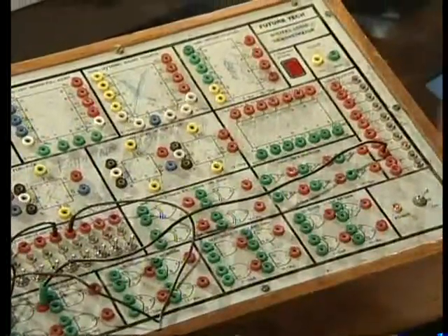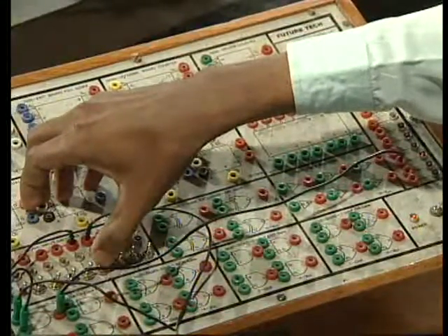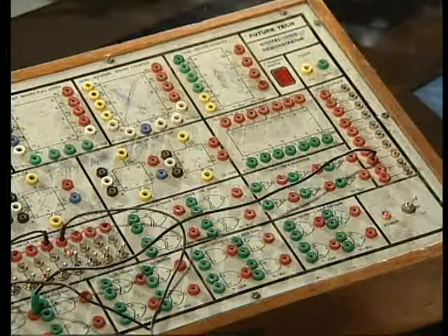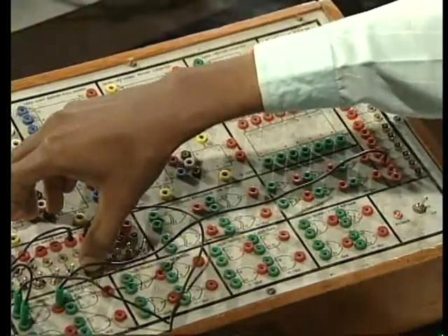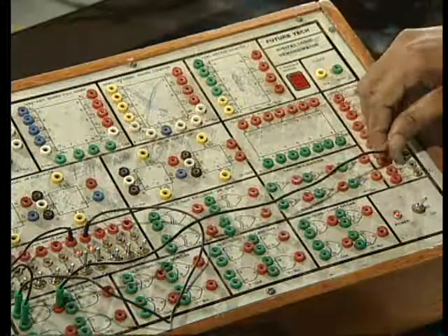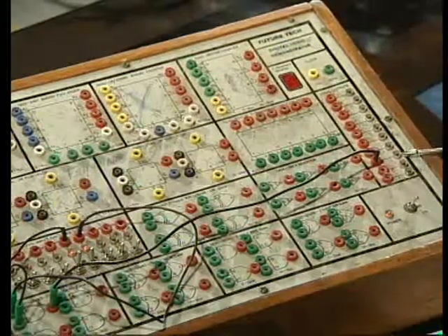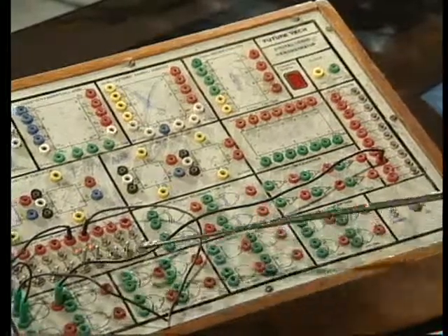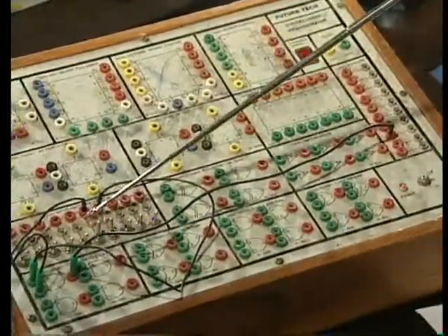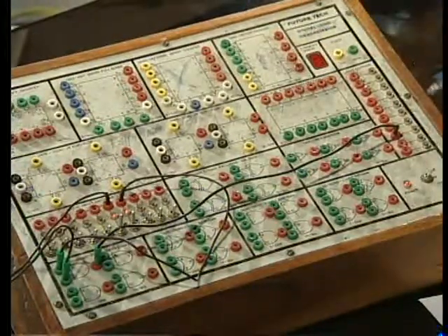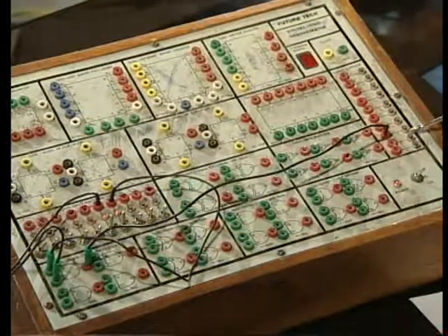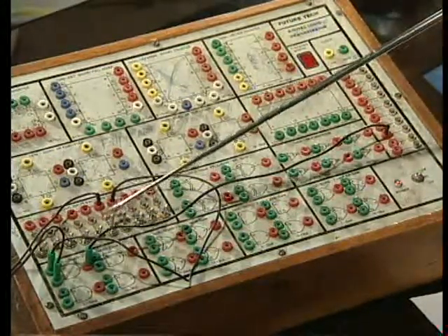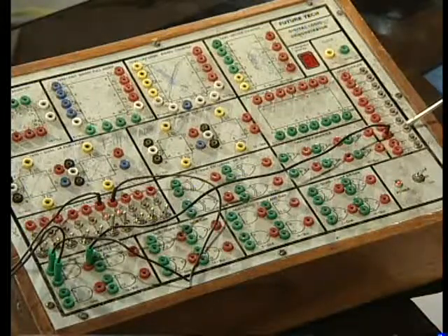Now, if one of the inputs is changed to 1, the output is still logic 1. If both are put to logic 1, the output is becoming 0. So, this is the verification of the NAND gate. So, you can observe that both inputs are high whereas the output is low. This confirms the truth table of NAND gate, that when all the inputs are high, the output should be low.